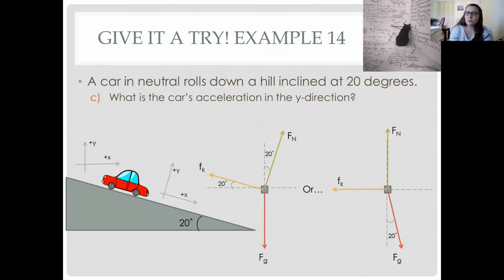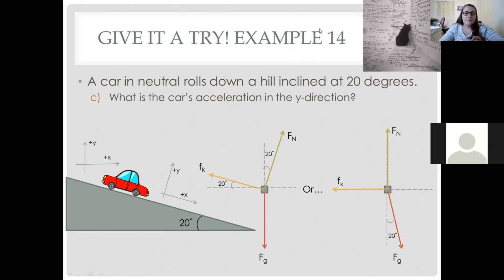It's just because of the way that we draw our free body diagrams, the way that we establish a coordinate system, either way, you're going to have an x component that's a sine and a y component that's a cosine. But here in this one, we have our y component that's the sine and the x component that's the cosine, like we're used to seeing. It's just super annoying when you're dealing with things on ramps like this. So that's why you just have to be aware of what you're doing. You have to pay attention. Don't go through these problems on autopilot. Make sure you draw a picture, and the picture will give you that clue as to what to do.